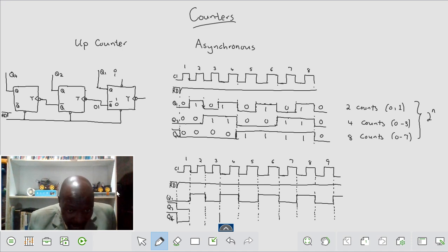It's actually a trailing edge for the next one, for node Q. So we are looking for a trailing edge. So this is a leading edge, it must be a trailing edge. So this will now toggle with each leading edge. This is a leading edge. It will toggle. Why? Because node Q is in the opposite state.